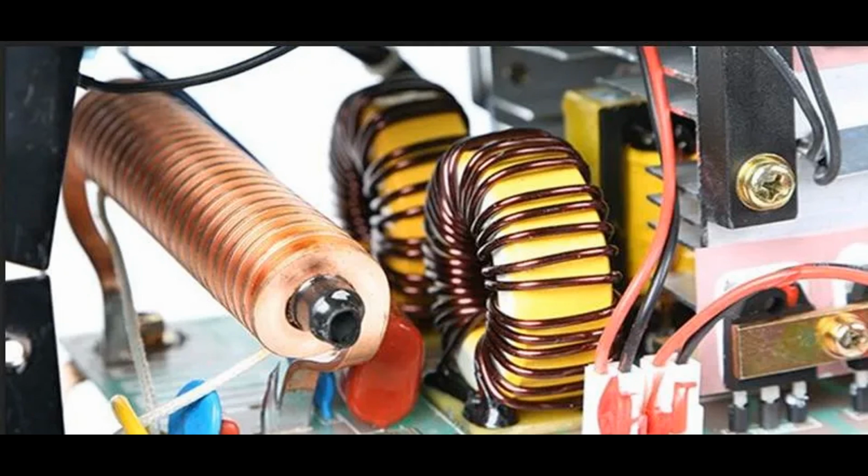3. Electromagnetic interference, EMI, suppression. A. Ferrite beads. Role. Ferrite beads are small ferrite core inductors used to suppress high-frequency noise and EMI in electronic circuits and cables. They are placed around wires or integrated into circuit boards to filter out unwanted noise. Benefit. They provide effective suppression of EMI, improving signal integrity and reducing interference in sensitive electronics.